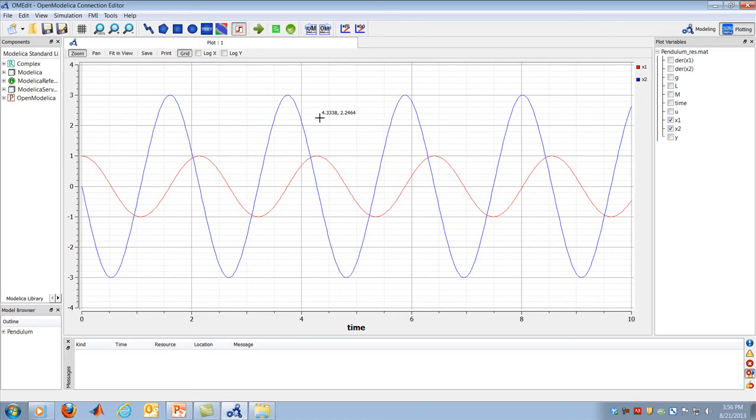We will find out later in the class that, very approximately, if you linearize a pendulum model around small angles, which the initial condition for this pendulum is not a small angle, but if you were to approximate the pendulum as having small angle initial conditions, the natural frequency of the pendulum is the square root of g over L, and so the position will equal initial position multiplied by cosine of the square root of g over L times time, the natural frequency, in radians per second.